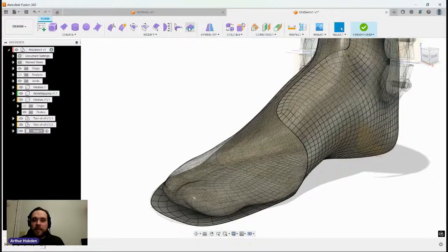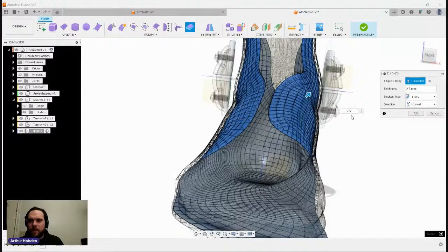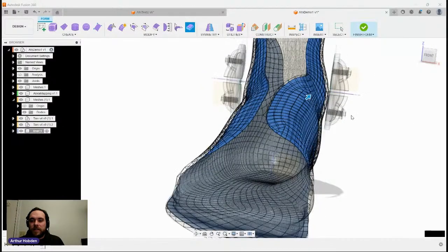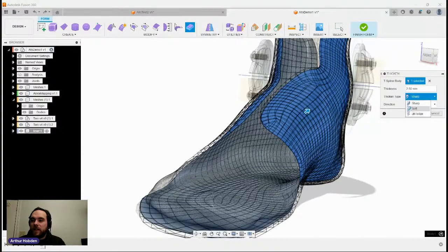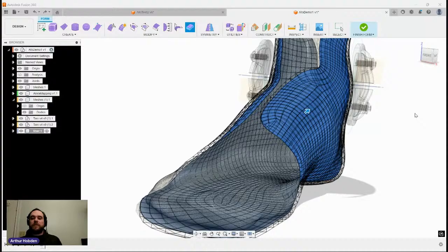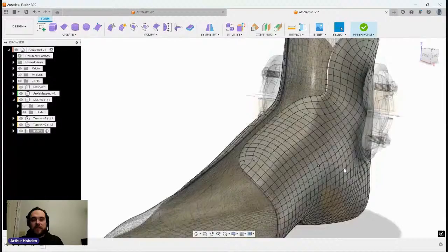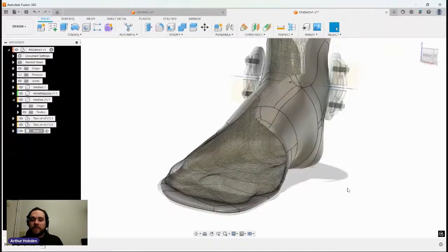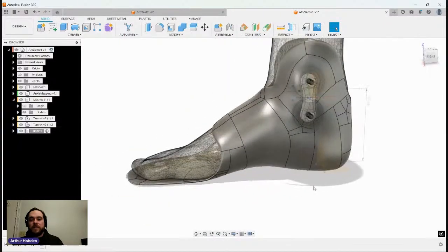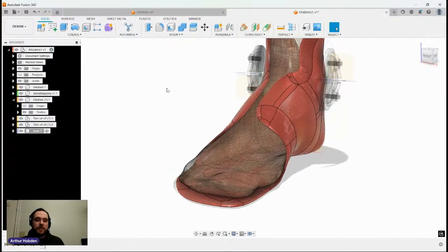So with that, let's do our next main command, which is we're going to thicken this out by, let's say, 2.5 millimeters. This again can be whatever you want it to be. I got to make sure that I turn on soft edging, which is also a really useful feature in Fusion, so that we can have soft edges for this part. So just like that, we have a completed solid, a 3D printable solid with nice geometry. If I hit OK, it's been auto surfaced, it's in place, we are good to go. So right here, if I hit A on my keyboard, let's quickly give this a material so we can see it. And that part technically would be done.